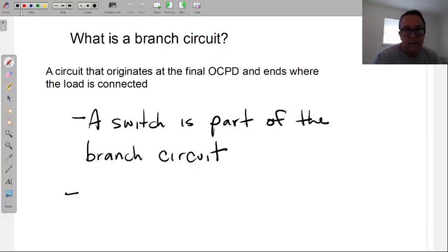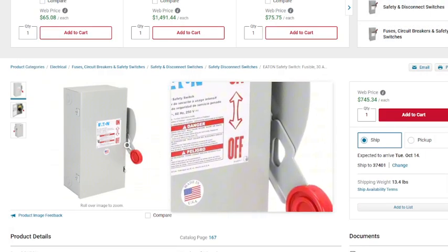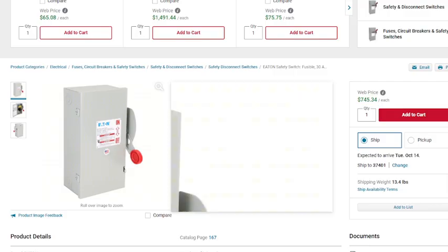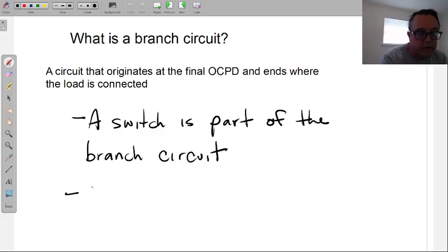Right now, you are very used to breakers, and you're getting introduced to fuses. If you haven't seen that before, the disconnect is where it houses fuses. It's a way to protect, going back one. This is a good one because that little spot that you see right there provides a perfect place to put your lock for lockout and tagout. Whenever you work around a lot of machinery, this is why they call it a safety switch. This has to be provided for motors, so I'll put it this way again.